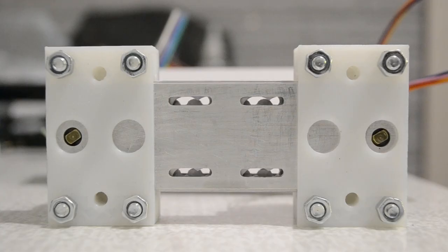Travel trajectory is defined by eccentrics mounted on shafts of 2 motors that run synchronously. All 4 plates have slots. Sliders have cycloidal cutouts, alignment plates have linear pass cutouts.